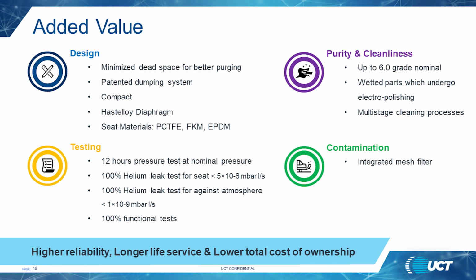Purity and cleanliness. Gas purity of up to 6.0 grade nominal, six nines. Wetted parts undergo electropolishing and multi-stage cleaning processes. Contamination: the integrated mesh filter prevents particles from causing creep or seat leaks.